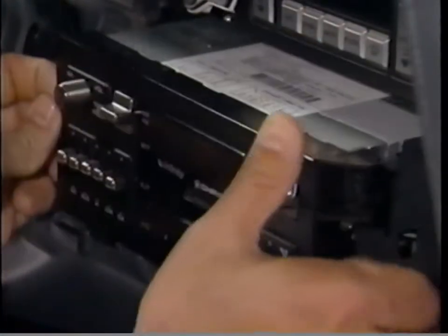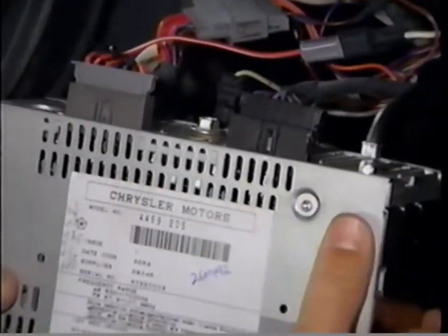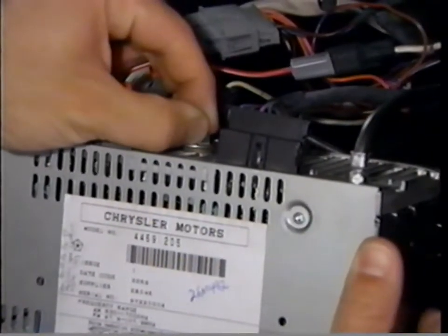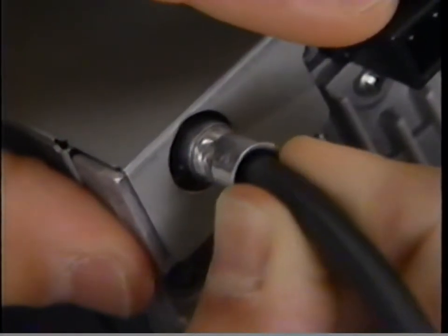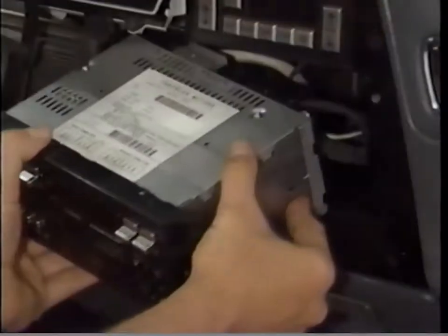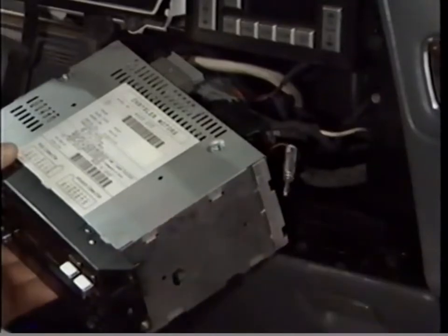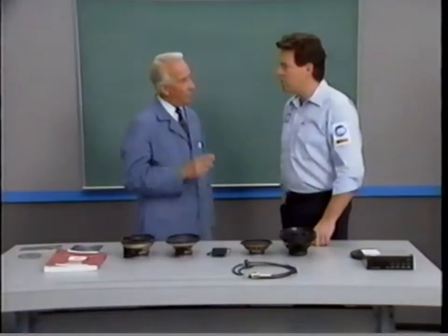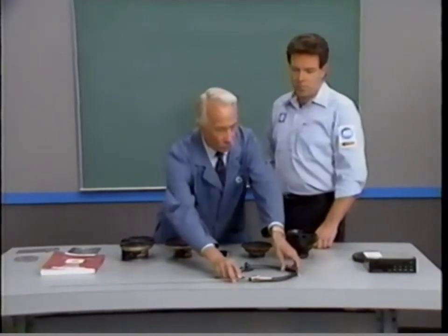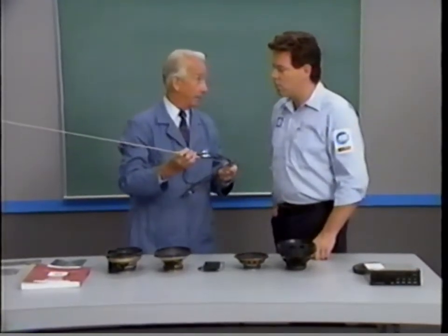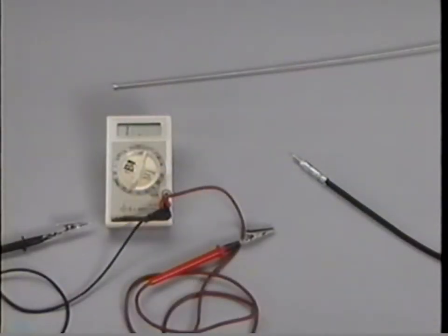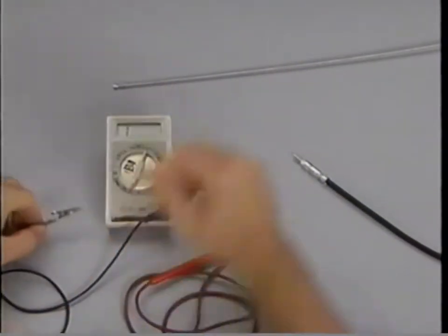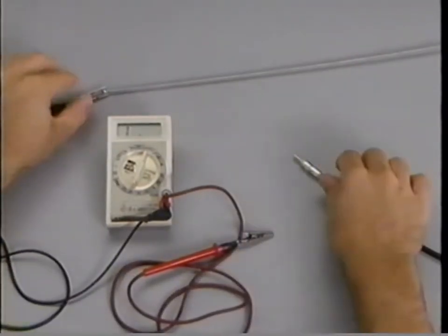How about intermittent or weak reception or radio noise that is not caused by RFI? Well, that sounds like an antenna problem. To troubleshoot an antenna, you must first remove the radio to see if it's grounded securely to the chassis. Also, check to see if the antenna plug is properly connected to the radio. Antenna performance may be tested by substituting a known good antenna. It's also possible to check short or open circuits with an ohmmeter once the antenna cable is disconnected from the radio. Continuity should be present between the antenna mast and radio end pin of the antenna cable plug.